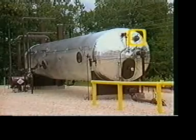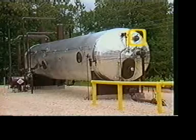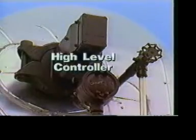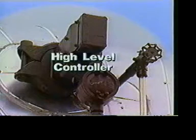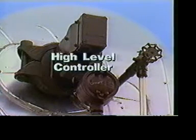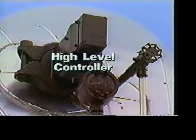The high-level controller ensures that the vessel never becomes completely full of liquid. It's designed to shut down the lease if liquid level rises above the set point. Shutting down the lease keeps the vessel from rupturing, which would result in lost revenue, environmental pollution, and a safety hazard.